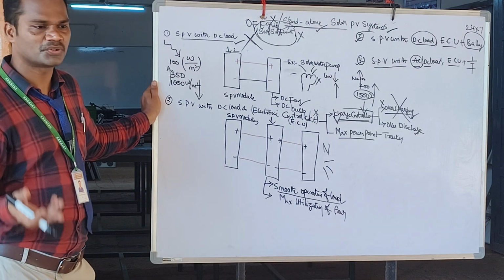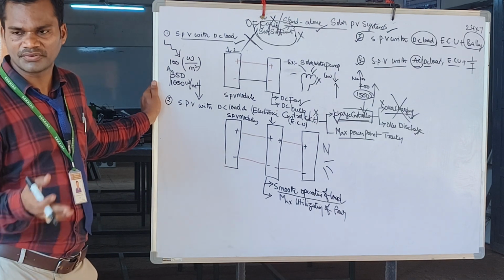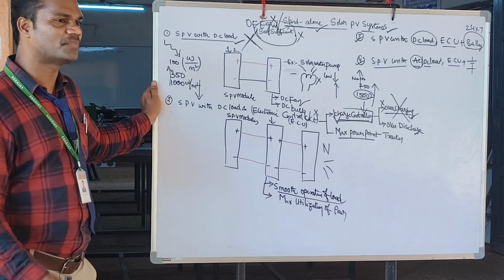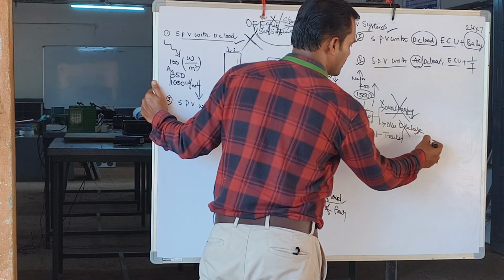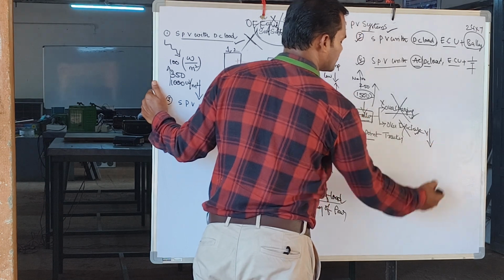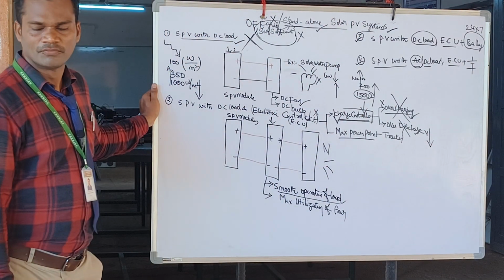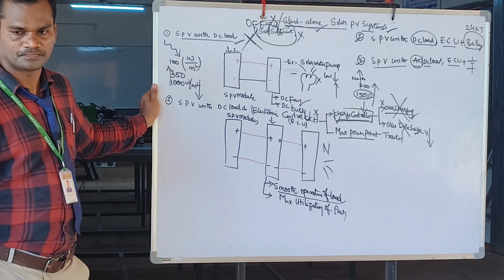If the battery is 100% full and the solar system still tries to charge it, automatically the life of the battery is going to be damaged. Similarly, if the battery is already discharged to 10% and still tries to drain, the life of the battery is damaged. It protects the battery from voltage over-discharge or voltage fall.